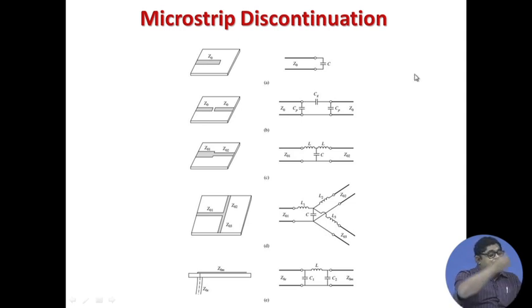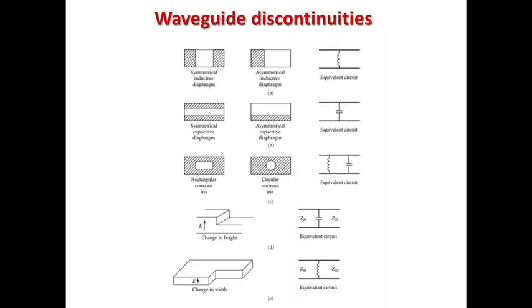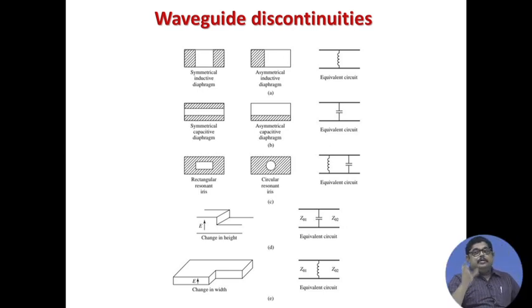Through S parameters you can model this; there are ways by which you can find it theoretically, and also you can measure it through the network analyzer, and the result will look something like this. I am showing this because in impedance measurement you can use these as your various loads. If you want to give a capacitor as a load, you can give either this microstrip or a capacitive diaphragm. We do that in the lab: we give the student an inductive diaphragm and ask him to find out what the load is, etc. So, with measurement he can do that.